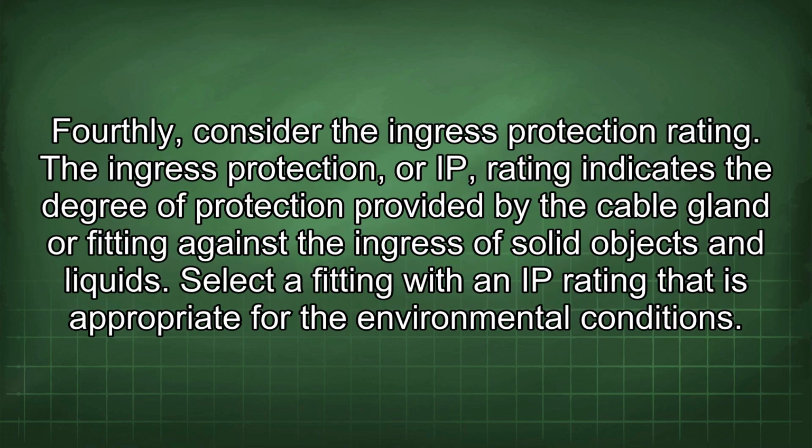Fourthly, consider the ingress protection rating. The ingress protection, or IP, rating indicates the degree of protection provided by the cable gland or fitting against the ingress of solid objects and liquids. Select a fitting with an IP rating that is appropriate for the environmental conditions.